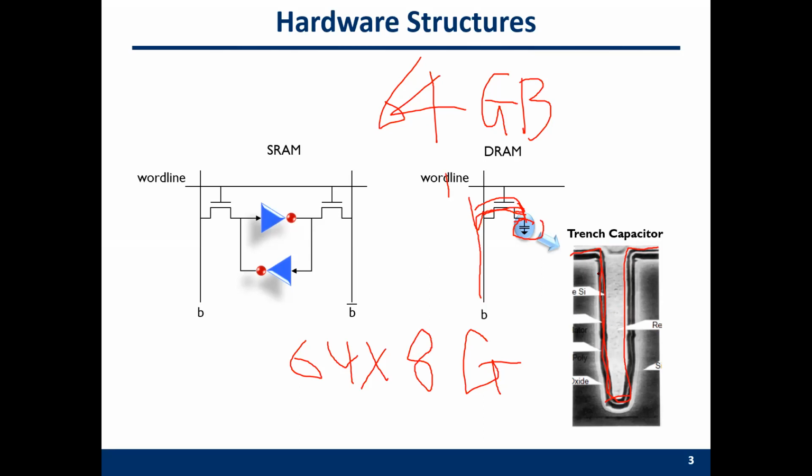And because we always have new process technology, now we talk about 22 nanometer. Maybe soon we will have 10 nanometer. Maybe now we already have 10 nanometer, maybe 8 nanometer. By this so-called process technology shrinking, this distance is reduced. So the distance between these 2 points is reducing. In order to maintain the same capacitance, we need to dig a deeper hole.